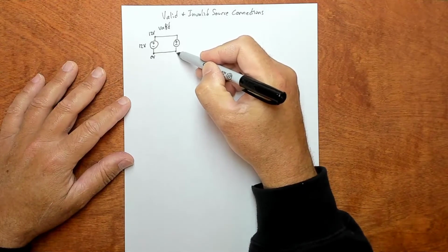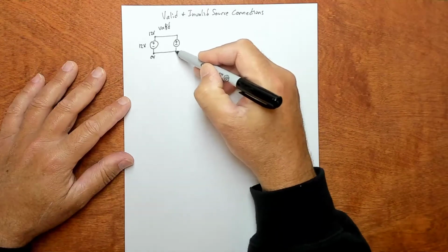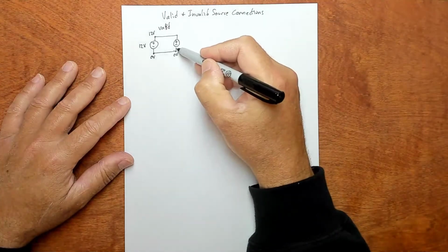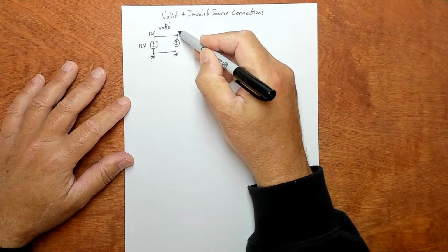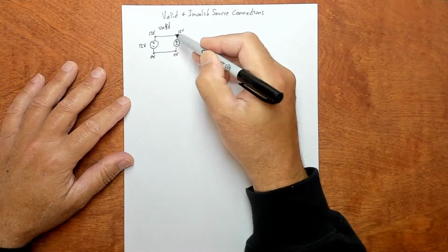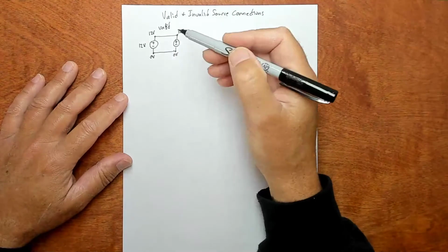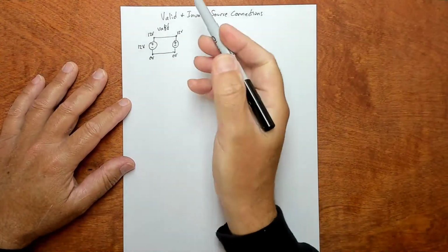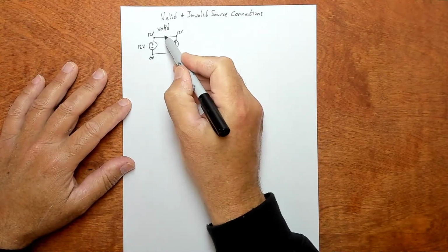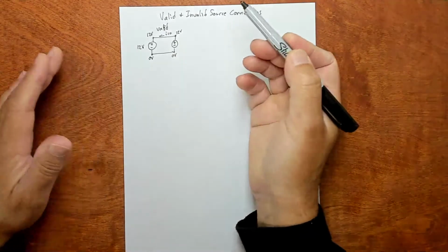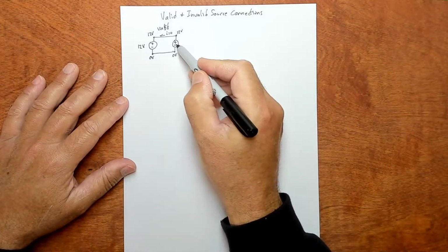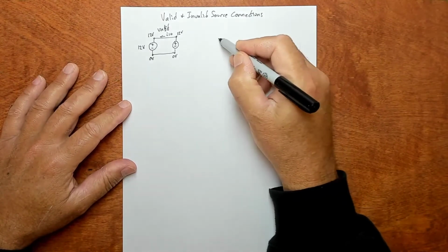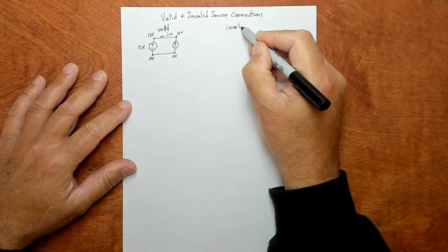And the same thing's happening on this side. This wire across the bottom is all 0 volts. You could write 0 volts here too if you want. And then we're going through this connection and rising 12 volts. So we've got 12 volts all across the top, 12 volts all across the bottom. There's no voltage changing here through this wire. There's no difference in voltage, so the current will be 0. And these guys will be happy to put out their 12 volts, and everything's okay. Everybody's happy.